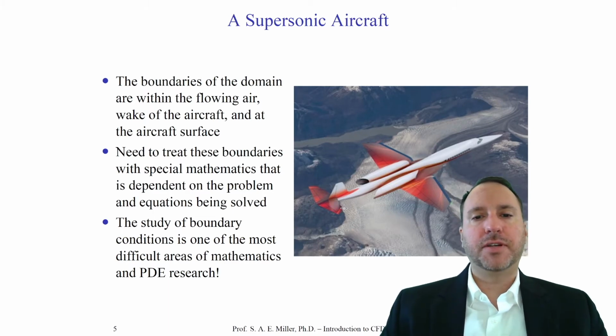Now remember, boundary conditions depend also on the set of equations we're solving. So for example, the wall boundary condition for the Navier-Stokes equations and the Euler equations might be different because the viscosity is 0. For example, the Euler equations should support a slip wall boundary condition.